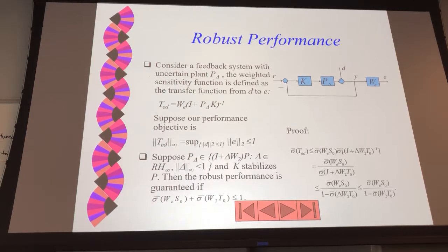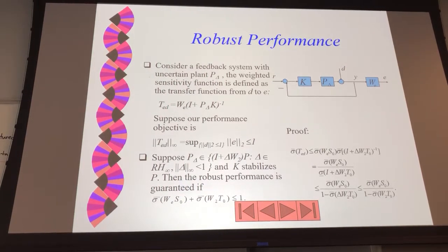You should write D to E from right to left. So don't write T_DE. That's not making good sense. Because when you have T_ED times D, you start to flow from here, and you get E. If you write T_DE, not T_ED, that means you don't really capture the MIMO nature of the system. Don't swap that. Write T_ED, don't do T_DE.